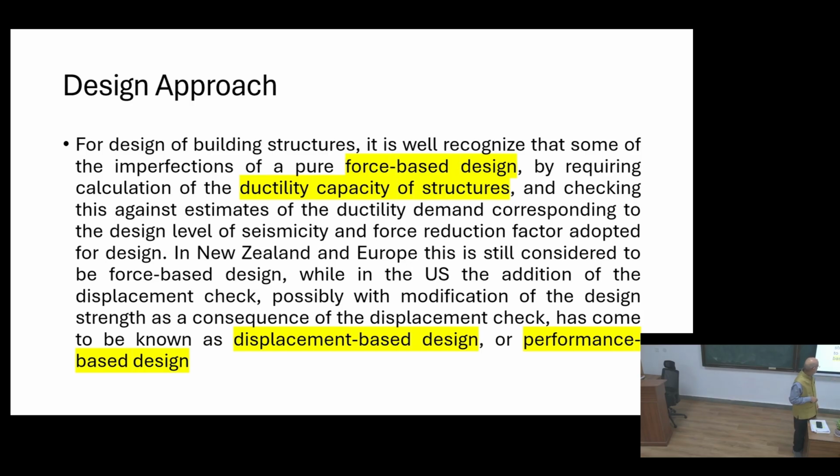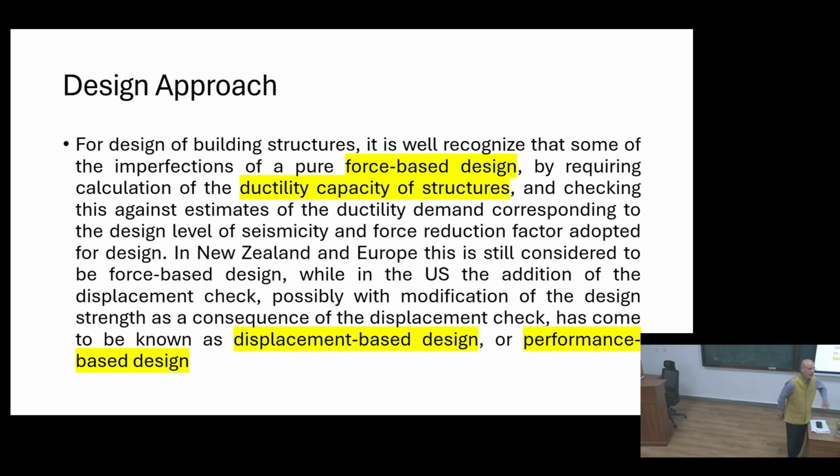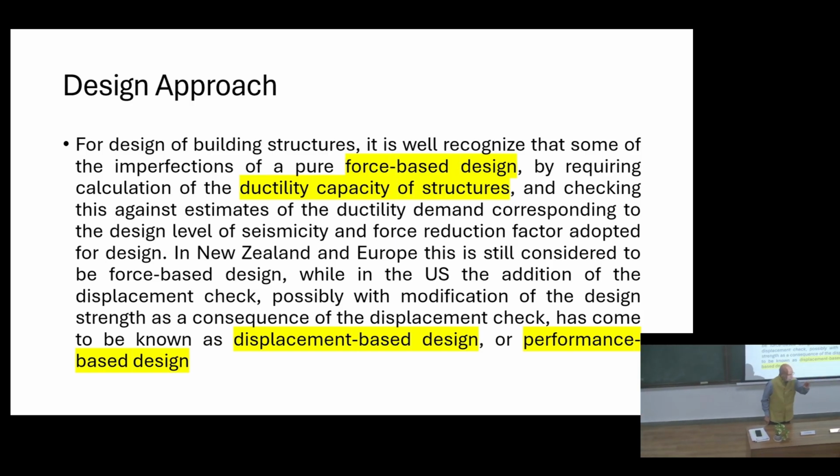Here I can mention the parameters which you use in design checking. Suppose you check how much displacement there is. I can cite an example: suppose a beam is there and you have loaded it, and by a certain guideline or exact analysis, the code says that for some factor, that much deformation is allowed in the structure. That is precisely a limit which you are fixing. So limit state is also a performance-based design, because you are fixing certain limits, like in the force-based design.